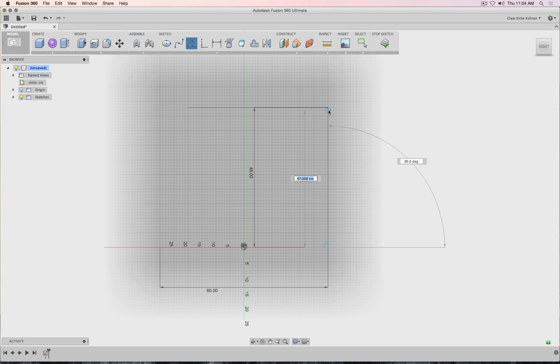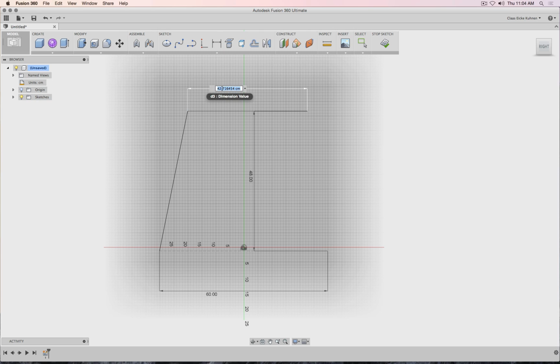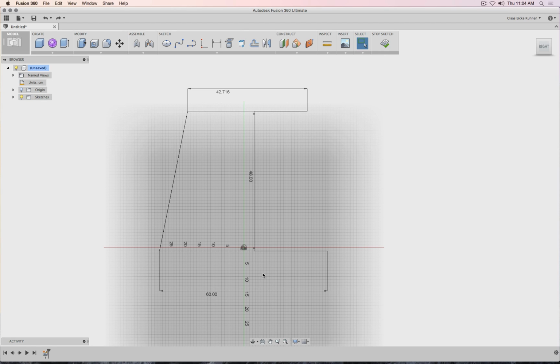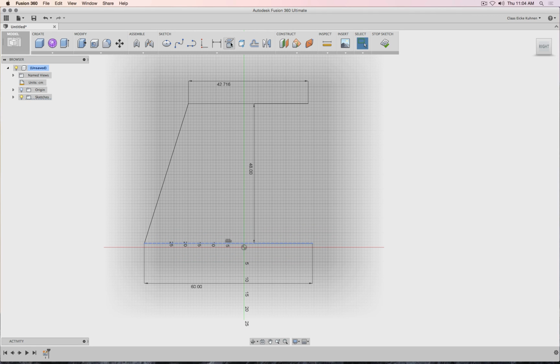And for example, I can create a line there and there. Delete this one. This I move maybe over a little bit. Can I not move it over? I should be able to move it. Oh, there, but then it changes the dimension. Okay, let's put in a dimension there as well, 50. Okay, then all this starts to work. Oh, awesome. Now my complete sketch moved. Okay, time to recenter stuff.